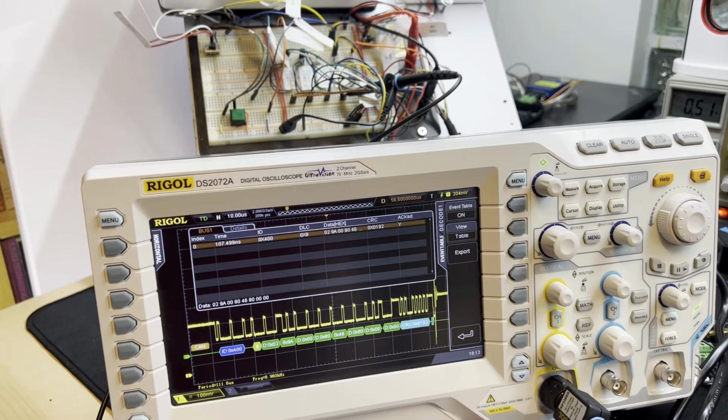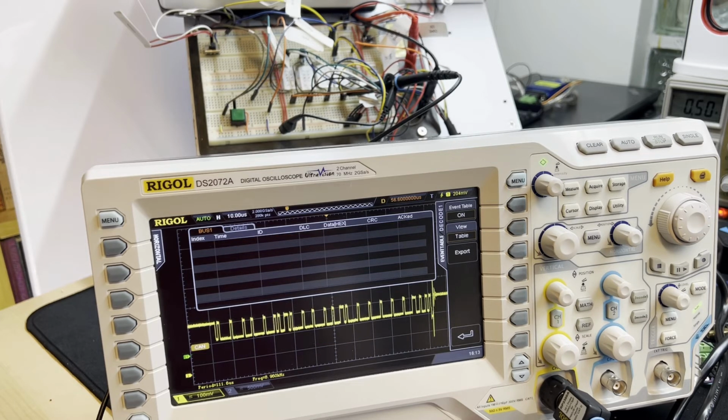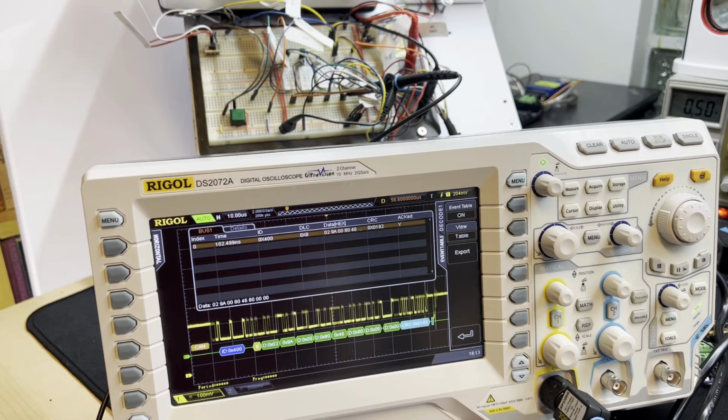Next, in yellow, we have the data length. For basic CAN this can be between 0 and 8 bytes. Then, in green, are the up to 8 bytes of data. And the message completes with the pale blue checksum which can be used to detect unintended corruption during message transmission. In the decode table we can see ACK to indicate that this message has been acknowledged.